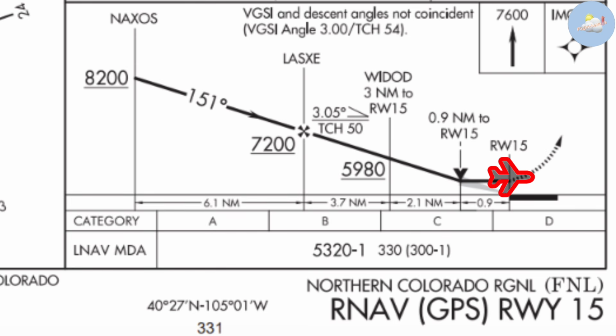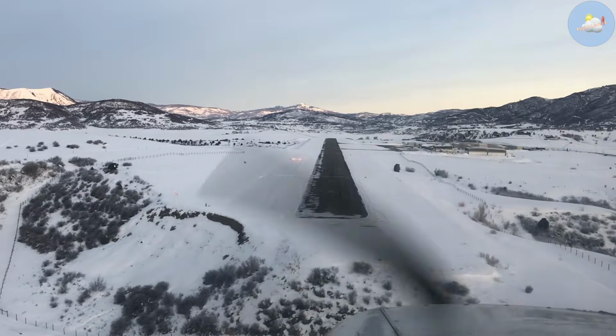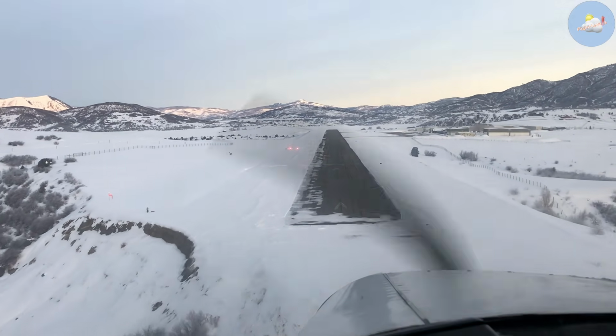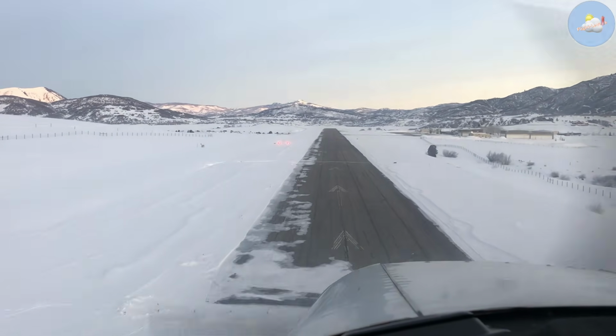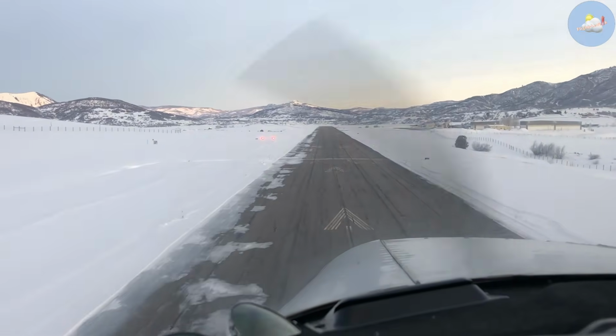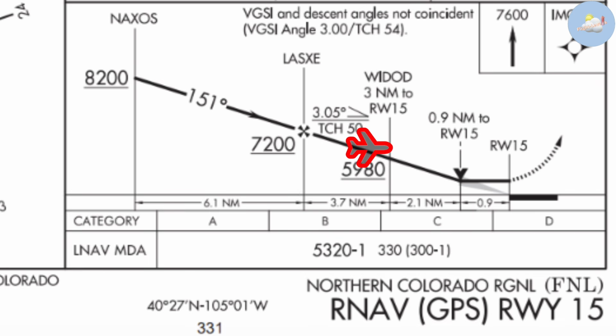However, if you do this, you are very unlikely to be able to descend using normal rates of descent and normal maneuvers onto that runway. So what you really should be doing, if you're following one of these +V advisory glide slopes, is once you reach MDA, if you cannot see the runway environment and fulfill all of 91.175, you should treat it like a decision altitude.